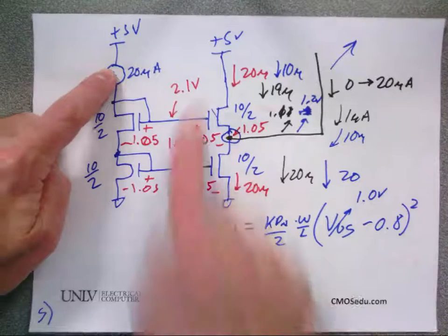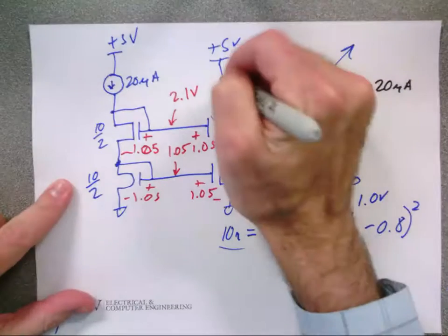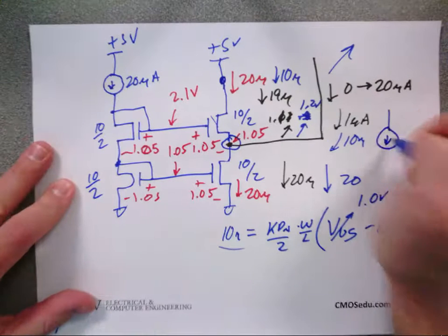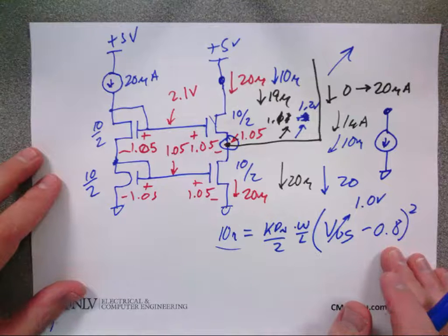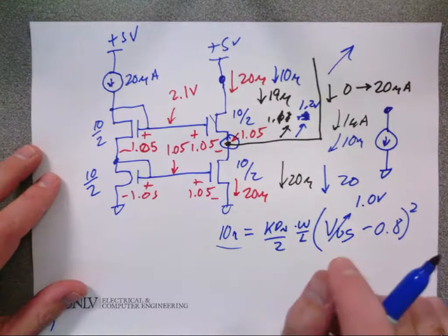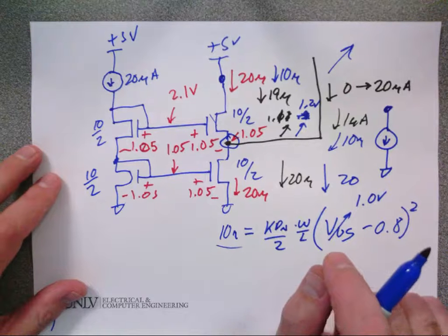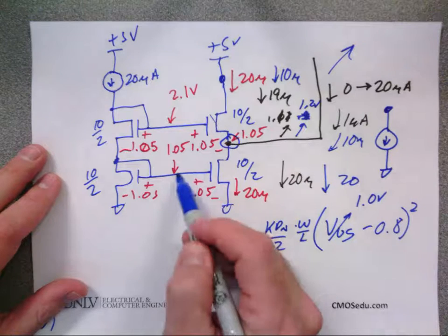And actually, this is how you make it. If I were to represent this side of the transistor, this point right here would be a current source like this. And that's how integrated circuits actually make a current sink. And I use PMOS for a current source. We'll talk about that in chapter 20. This one? Nope, never change.